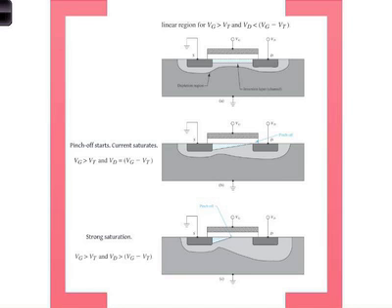These negative charges come about two ways. First, the p-type material has lots of holes. First thing that will happen when you have positive charge here is that the holes will get repelled. They move away from that interface. Positive charge, they repel. When that happens, you expose the acceptor ions, which are negatively charged. So you expose uncompensated acceptor ions. It essentially creates a depletion region. You push the holes away, you push away the carriers, it's a depletion region. That's basically this light gray region.